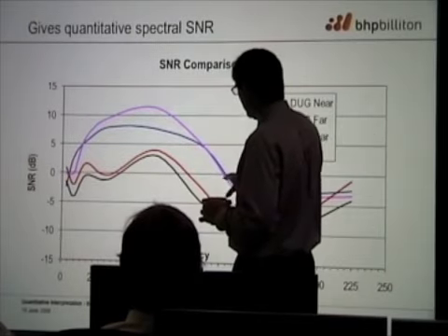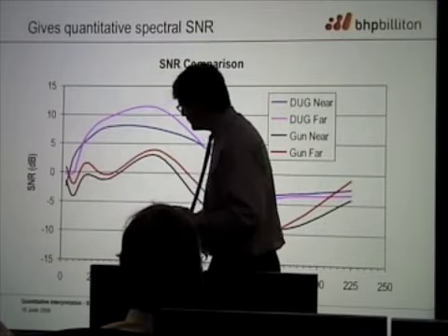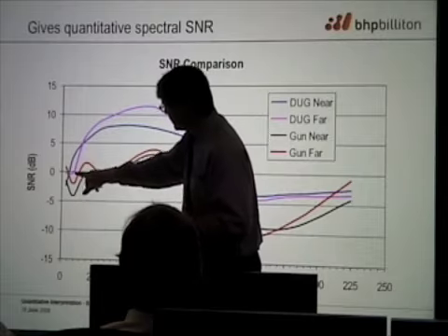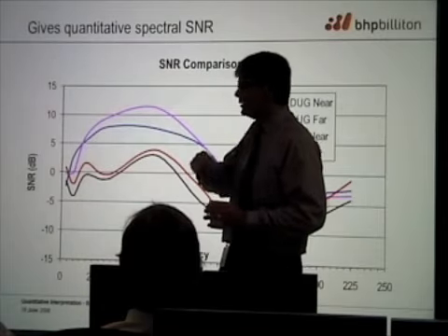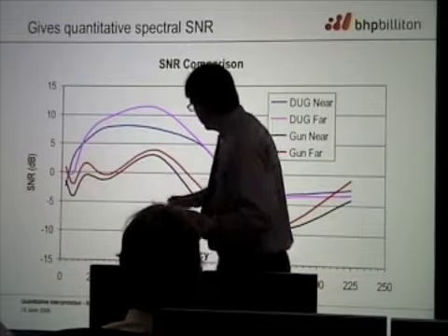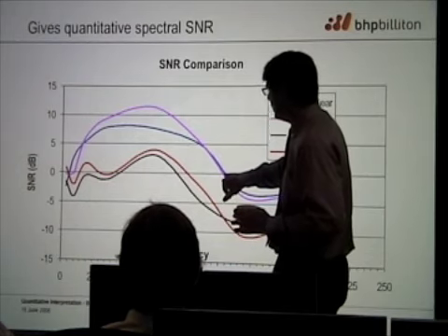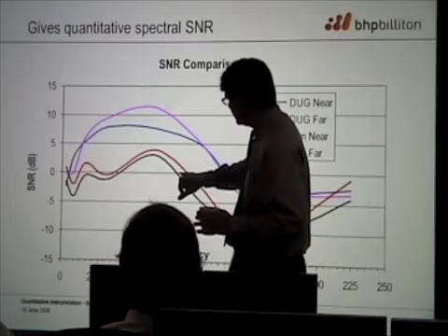And in fact, you can easily see now that the bandwidth, because we have a signal-to-noise ratio as a function of frequency, for this reprocessed data that Mark worked quite hard on, goes from this point to this point, which are the zero crossings, where before, I don't know, this bump, it probably goes from here to here.